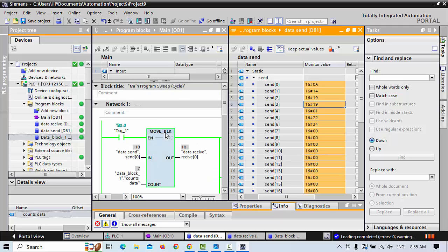And this block move instruction means the same. This is the function. You want to send a complete block from 0 to 5, 0 to 6, 0 to 10 or 0 to 15, however many blocks you like to send at one time with one execution, you can send from this move block. This is a very interesting and very helpful block command in the TIA Portal, and you can use it for your own purpose anywhere in the program. Maybe I hope you completely understand this command.